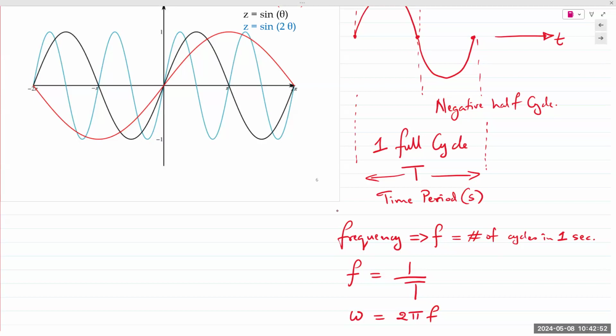So that's a good question. How are the power outlets connected in our residences and everywhere else? They are all in parallel. If it's in series, they wouldn't work without something being plugged in there. Series connection means everything needs to have a closed pathway, so it wouldn't work unless something is connected. So everything is in parallel. So it's all cumulative effect.